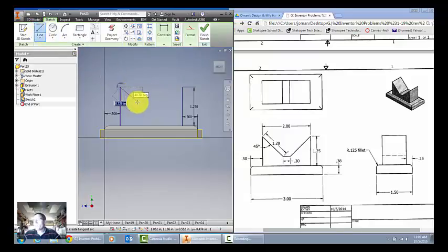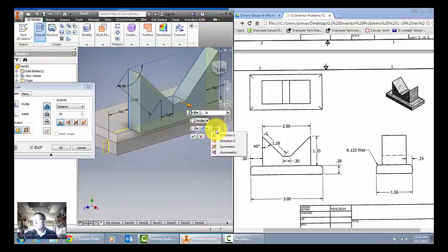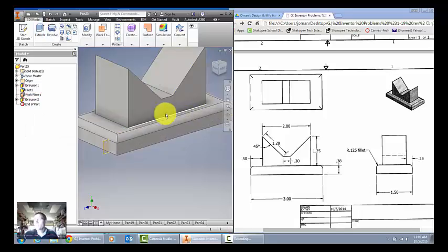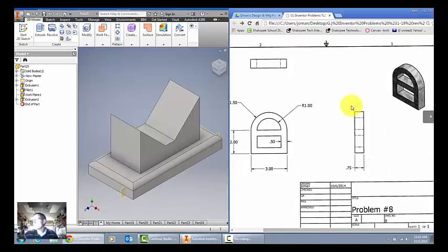I'm going to use the line tool to draw 45 degrees, 1.2. 0.3 over, and then I'll finish the box, finish the sketch, extrude, change the direction to direction 2. Looks like we're extruding this thing. It doesn't exactly say, so the whole thing's 1.5, subtract 0.25, subtract 0.25. I would say we need a 1-inch extrusion to happen. That appears to be right. And problem 7 is done. On to problem 8.